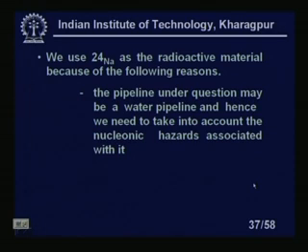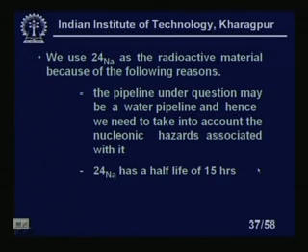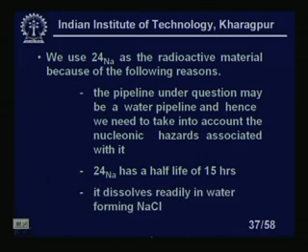The pipeline under question may be a water pipeline, hence we need to take into account the nucleonic hazards associated with it. It should not be very hazardous. Sodium 24 has a half life of 15 hours, so it is very short. It dissolves readily in water, making sodium chloride, that means common salt.